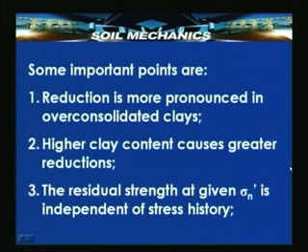So, some of the points that arise from this discussion are: there is a more pronounced reduction in over consolidated clays from peak to residual. And another point that is worth mentioning is, higher the clay content, greater is the reduction from peak to residual. The drop in strength with displacement is more if the clay content is more in the soil.